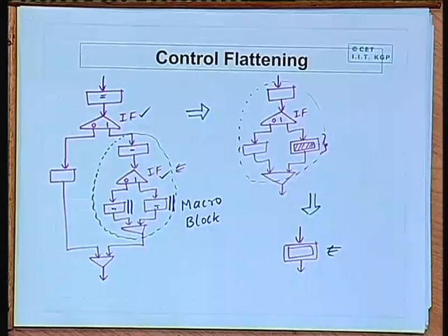So, actually you now have some kind of a hierarchy of control signals being generated in a hierarchy of modules. This helps in many cases. The bigger the size of the FSM, the more flip flops you need to store the state, and the more hardware will be needed to generate the control signals out of those states. But if you have this hierarchy, which can come very naturally from a description, it can help a lot.